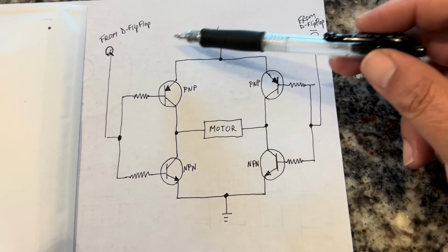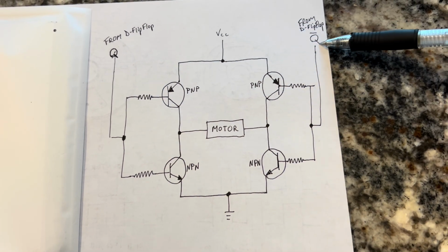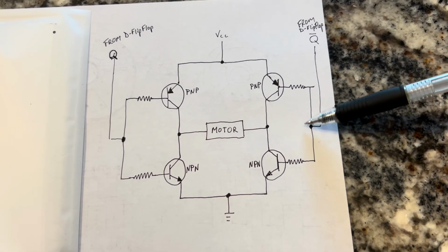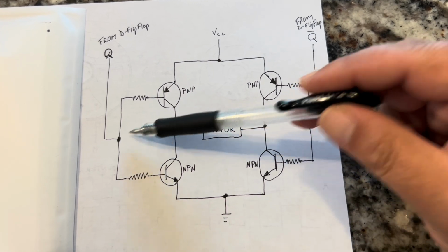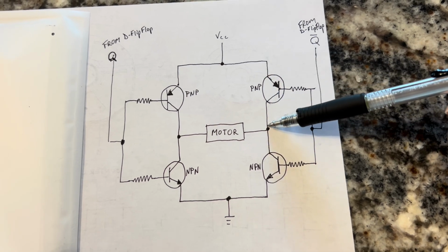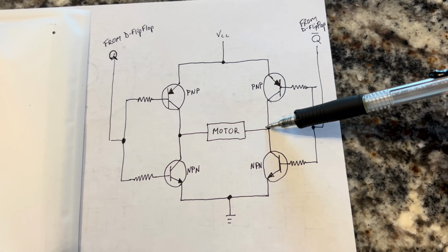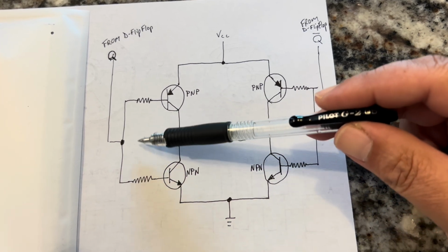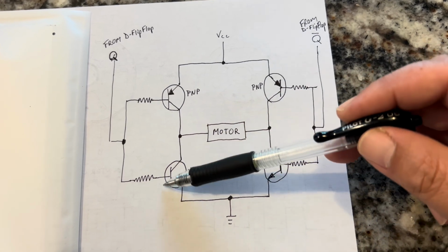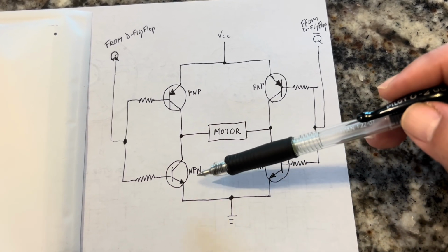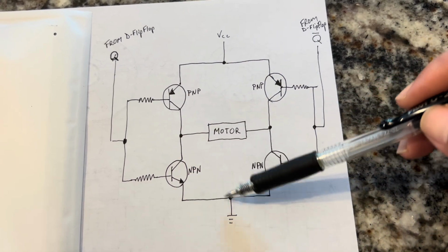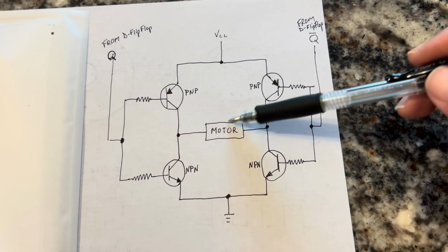And so what happens is when you flip the motor controller to clockwise position, you want the motor to spin clockwise, the Q will go on and the Q bar output will go off. This provides a logic 0 here and a logic 1 here. A logic 0 at a PNP transistor will open up that transistor, and a logic 1 on a PNP transistor will turn this one off, and a logic 1 here will turn this one on. And so the flow of the current will go like an H bridge, and it will rotate clockwise.